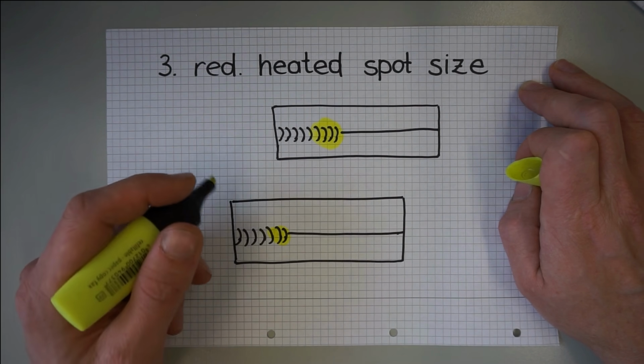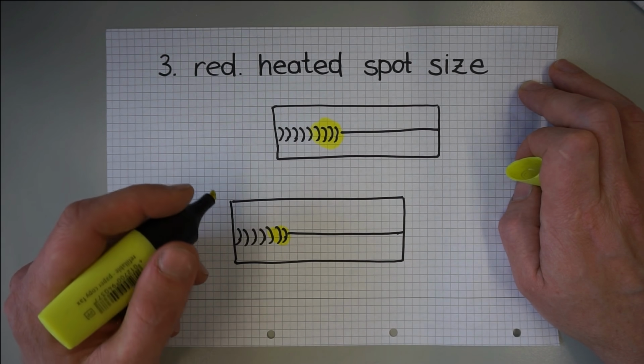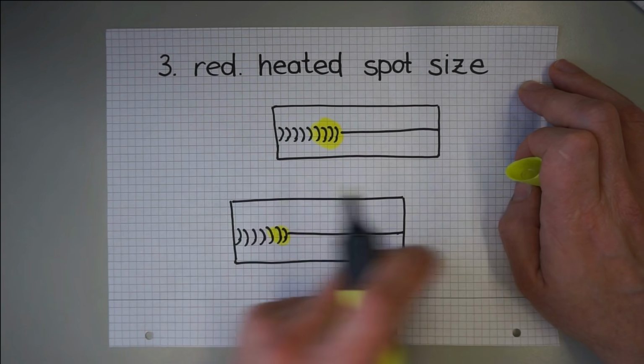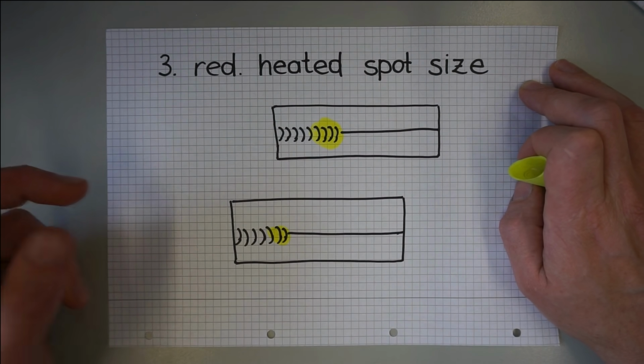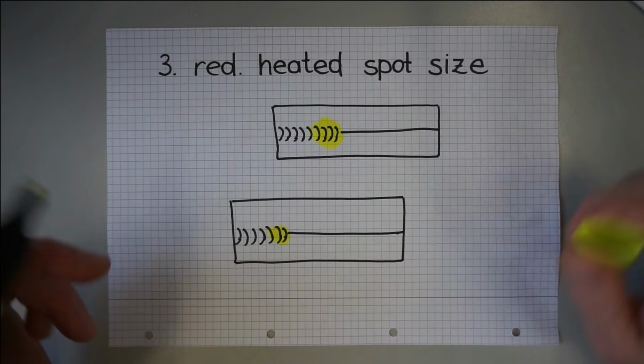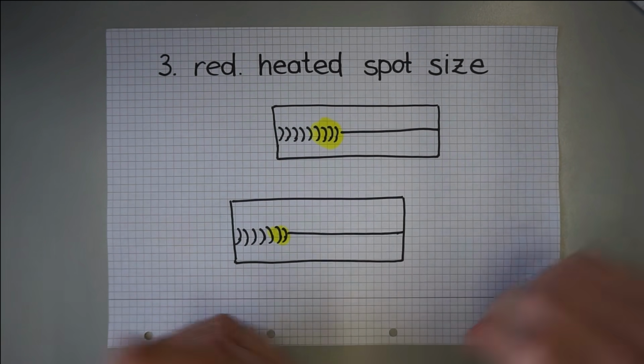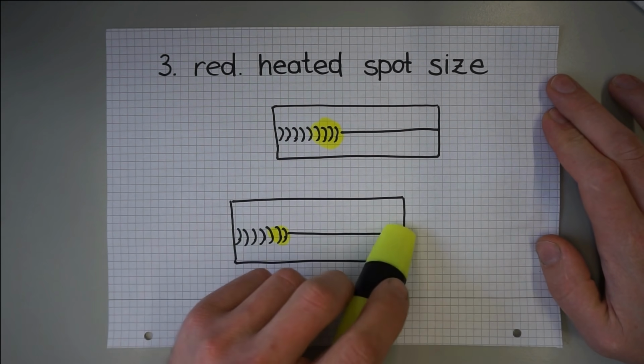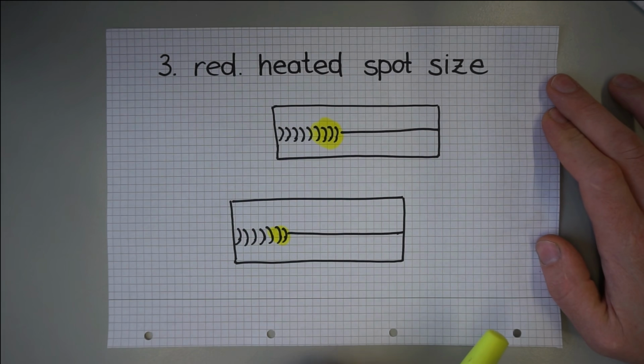Of a similar nature in this regard is the old school rule of increasing travel speed, or welding faster if you will. The thought behind it is the same as for pulse welding. As we travel the torch faster over the workpiece, the heated spot at a given location gets less time to grow.